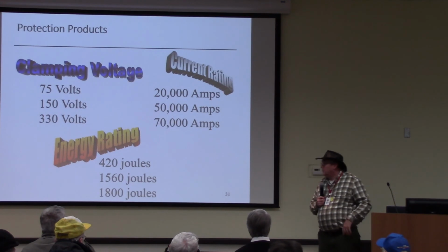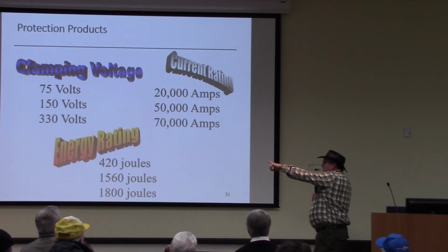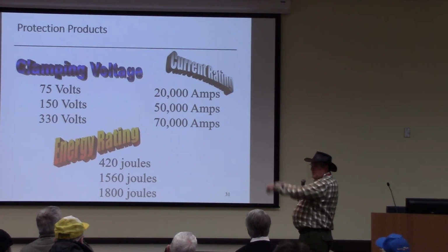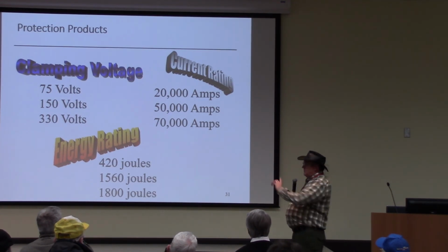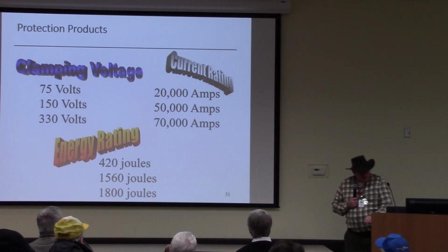But first off, you want to pick that. If you're going into this, you pick your highest energy rating. Then you need to make sure you're meeting your clamping voltage. And those two things there will set your current for that test.